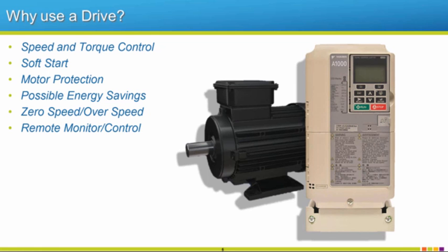There's even the ability to have a zero speed servo-like characteristics for an induction motor. And also the ability to run high speed, so above your base frequency, as long as your motor can handle that. We also have the ability to do remote monitoring and control through communications. So you can monitor your system at your desk.